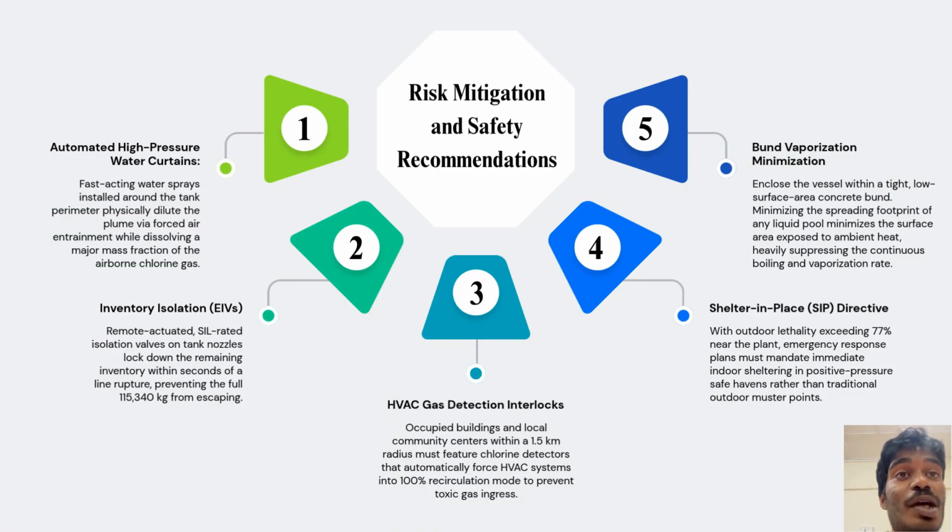Moving to mitigation, our data proves that traditional outdoor evacuation is a fatal mistake. Near-field lethality exceeds 77% across all weather cases. We must shift our strategy from reactive fleeing to engineered defense in-depth containment. On the hardware side, we implemented automated high-pressure perimeter water curtains to actively dilute and dissolve the airborne chlorine cloud, paired with remote emergency isolation valves to stop the release at the source.